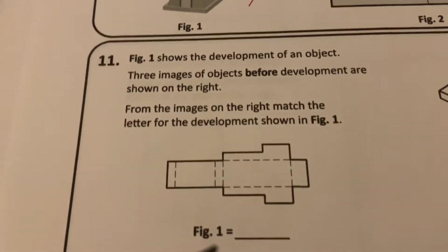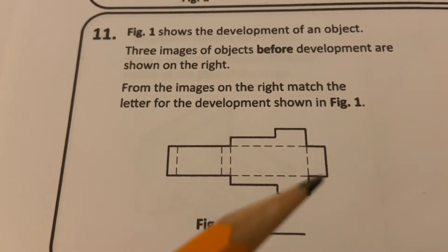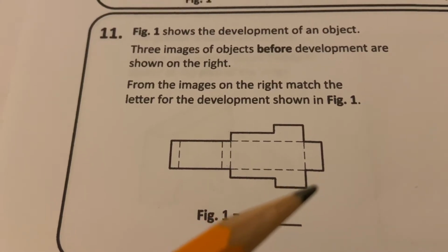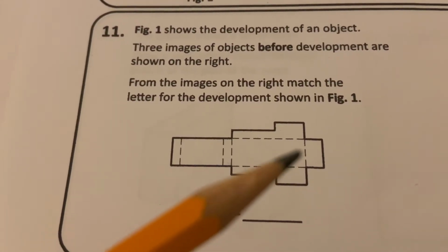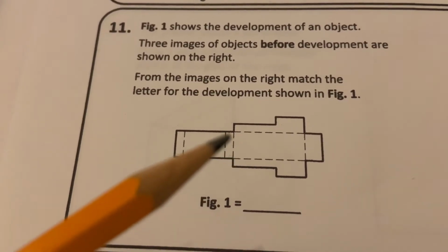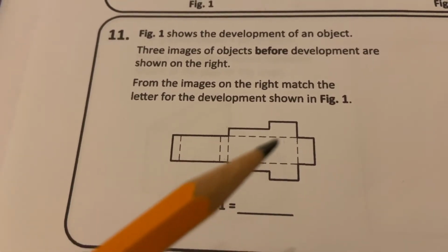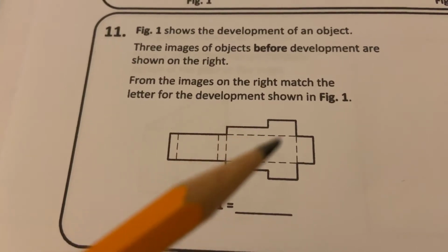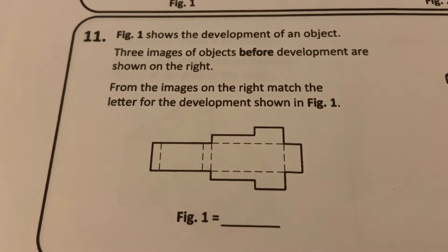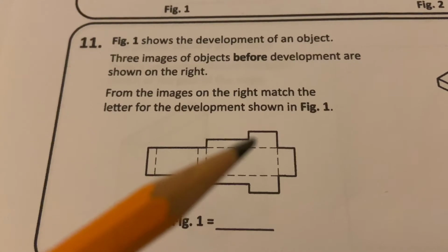So if you look at this here, if you fold up that side, and if you fold up that side, and if we fold up the back, that means that this corner is going to meet with this corner, and that's going to create a right angle at the back, and that's fine. Now if we look here, we have this front surface which is going to fold up along there. We're going to have this surface here which goes along there, and then we have this little upturn here. So the object when it's folded together is going to be enclosed except for this portion at the top.